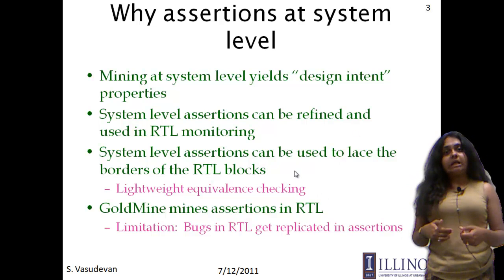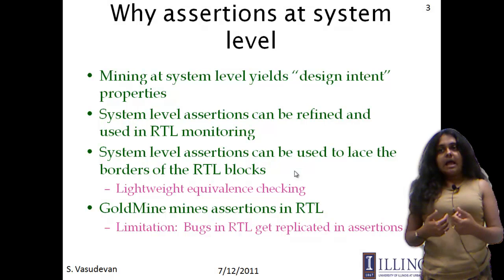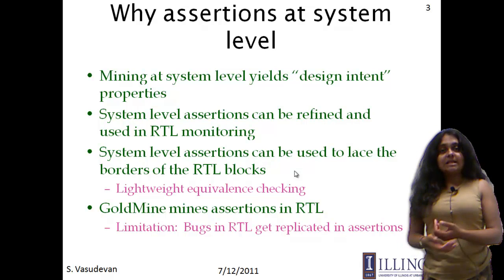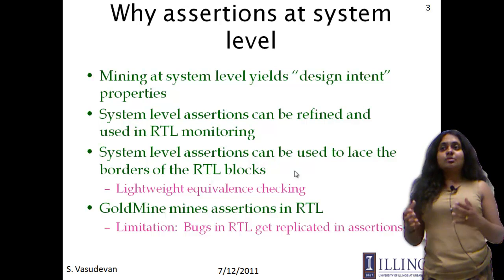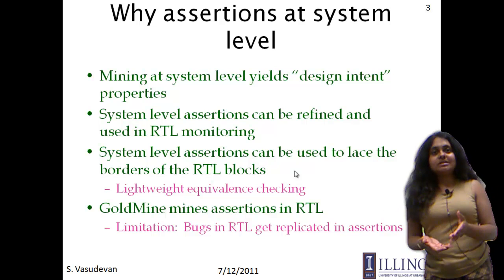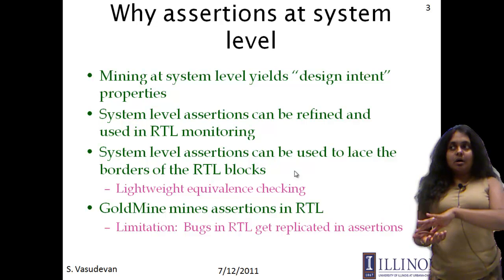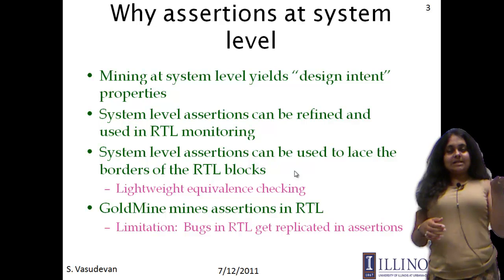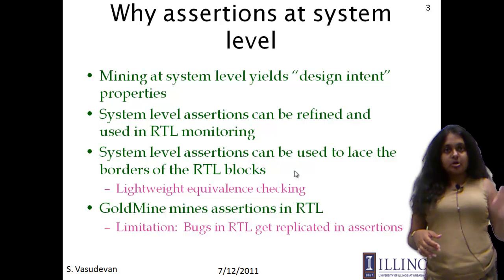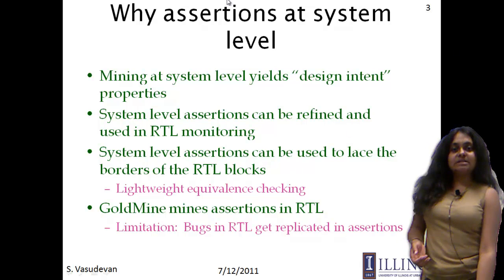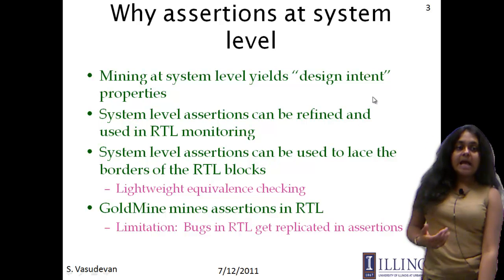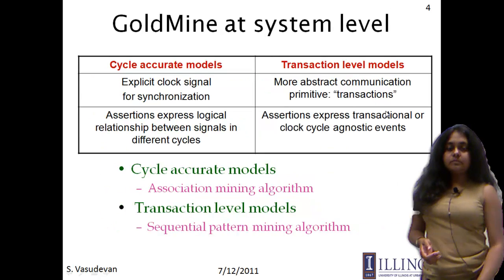Another reason is that our previous work did assertion mining from RTL, and the limitation there was that we were generating assertions in RTL from the RTL itself, so a bug in the RTL could get replicated in the assertions. And so a logical next step in our research was to push this analysis upstream in the whole design cycle, and that's the reason why we would like to mine assertions at the system level as well.